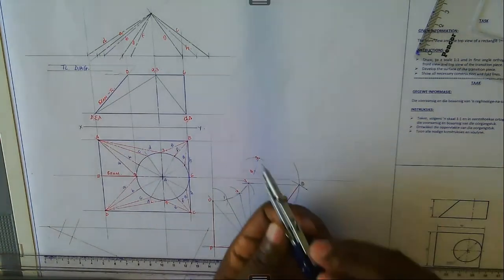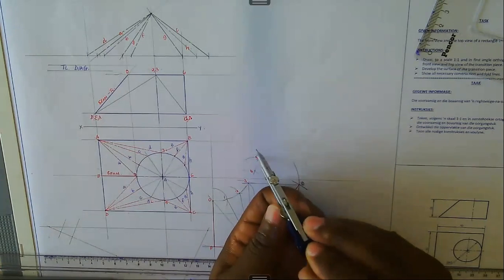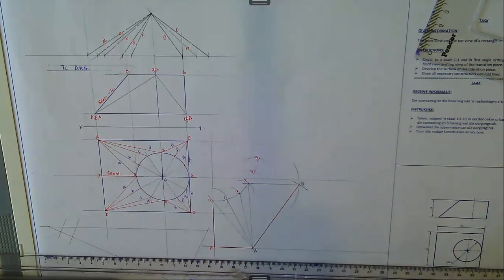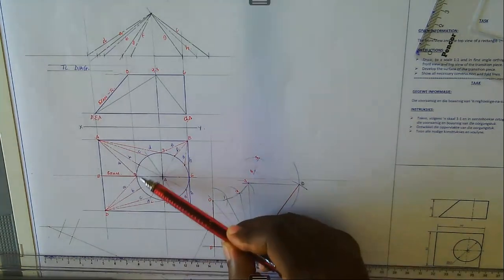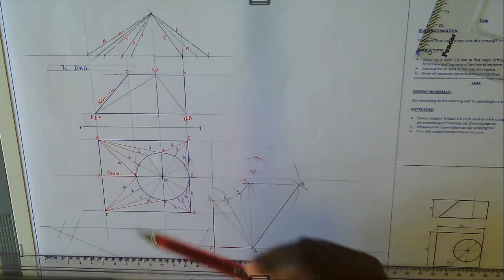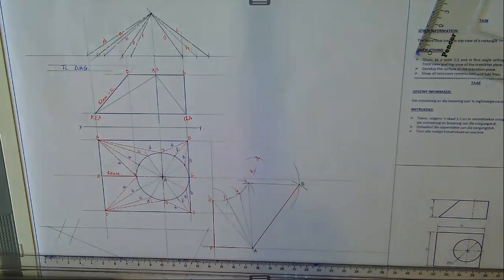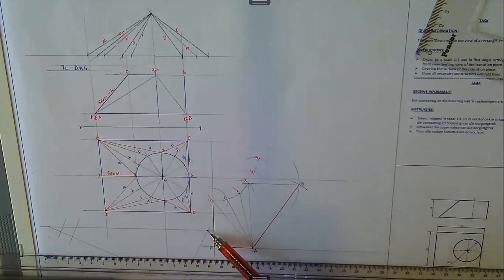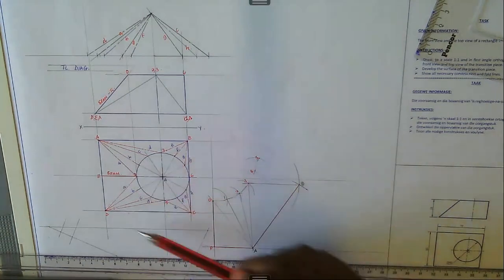Stand there as well. This is not going to change, it's consistent. Remember, like I said, you can use this measurement, what we refer to as the rule of thumb. It's not correct, but it's acceptable. But if you want to be more accurate, you find the circumference, pi times diameter, divide that into a number of equal parts, in this case 12 equal parts, the same divisions that we have here.